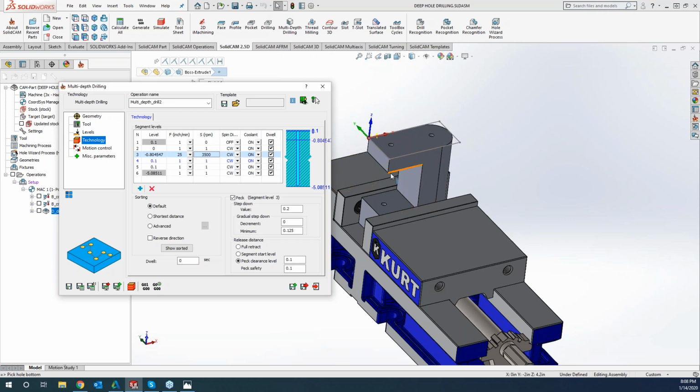And now there's no point in doing a drilling cycle through this entire window here because that window is there and we don't need to drill through there. So from that portion on, maybe I want to turn my spindle off or reverse my spindle. So from my negative 800 thou down to this spot right here, I would like to have my spindle set to counterclockwise at maybe 10 RPM.